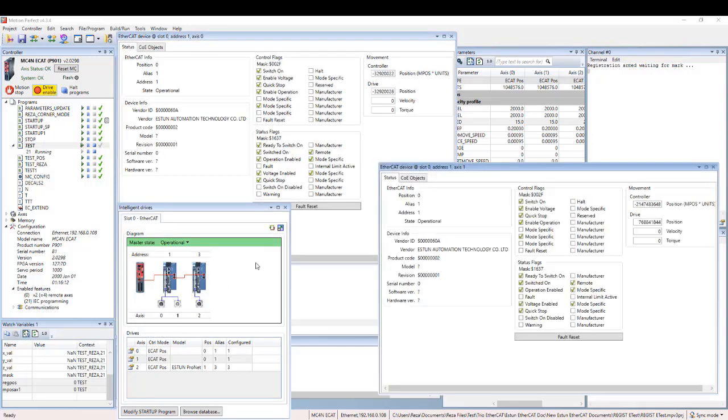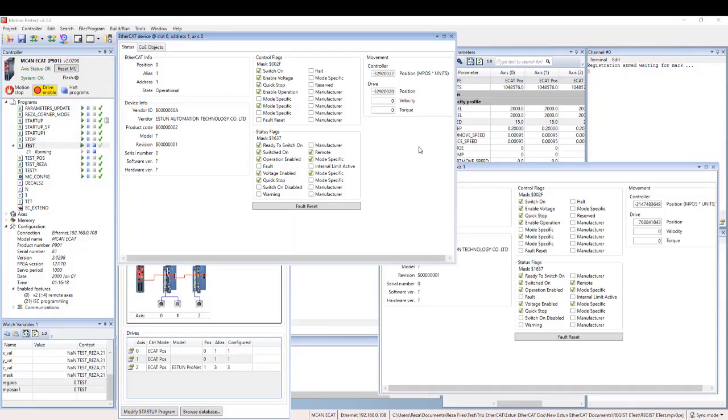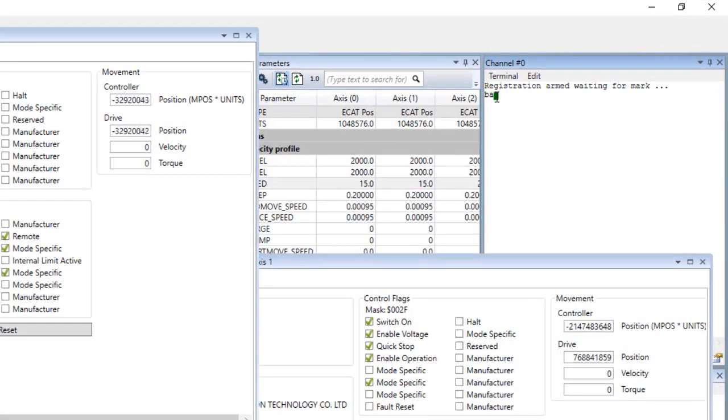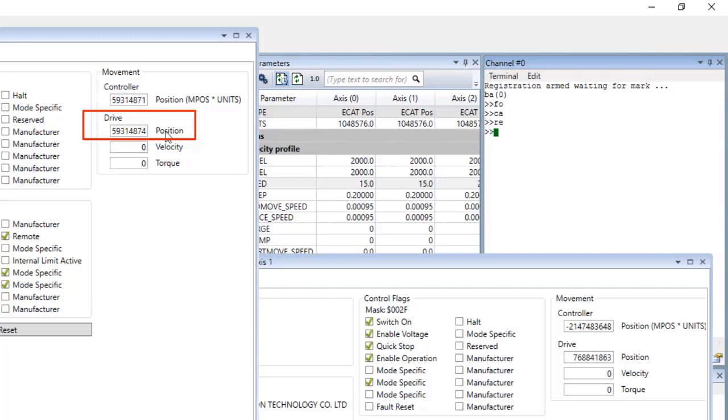As you see here, we have a screen for each motor, and here I can just choose base 0, for example, which is the first axis, forward this one, and you see the motor is rotating. Cancel, and reverse. You see the first axis is rotating in the reverse direction.